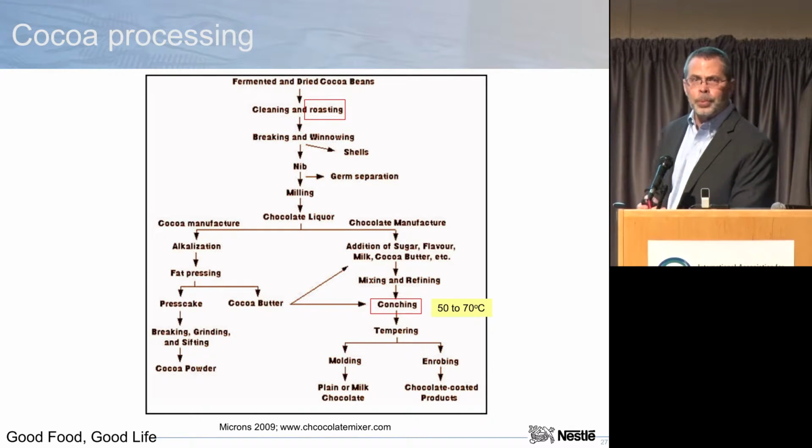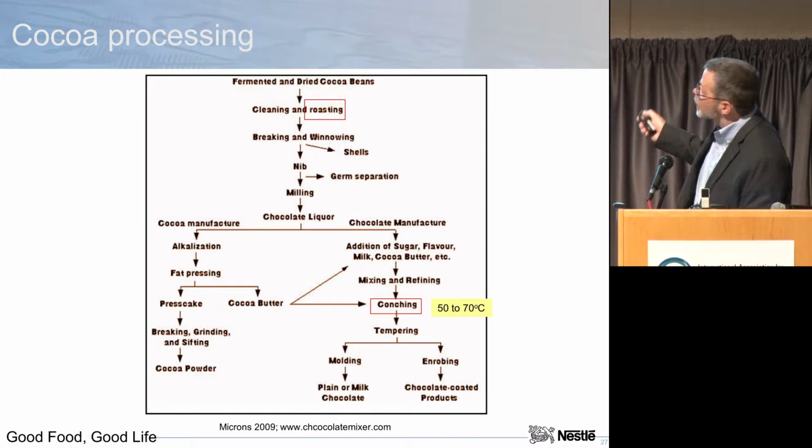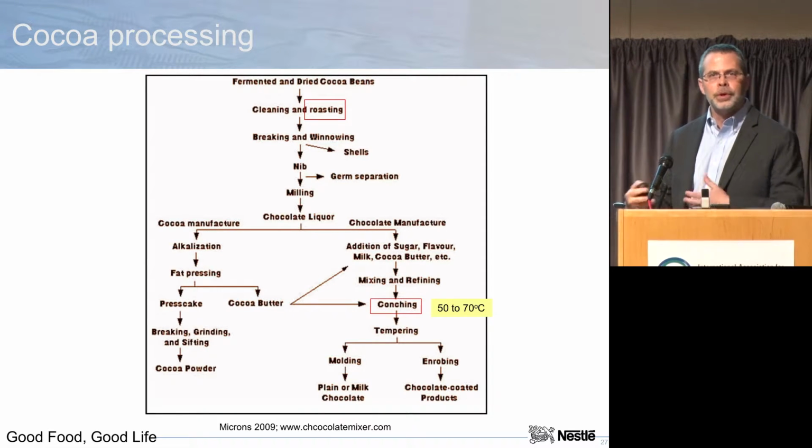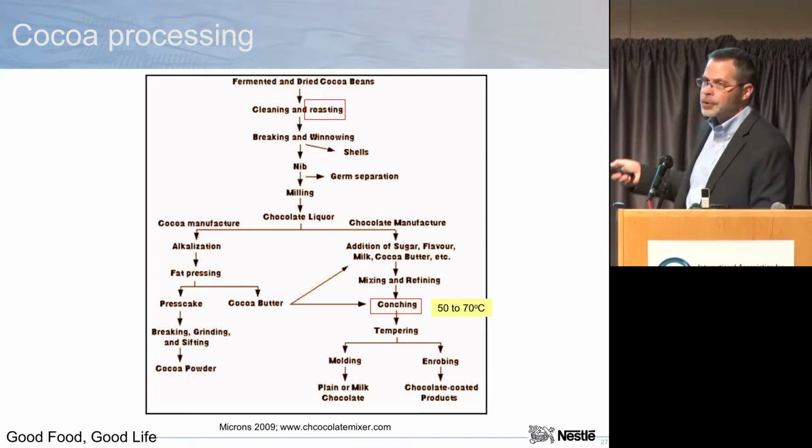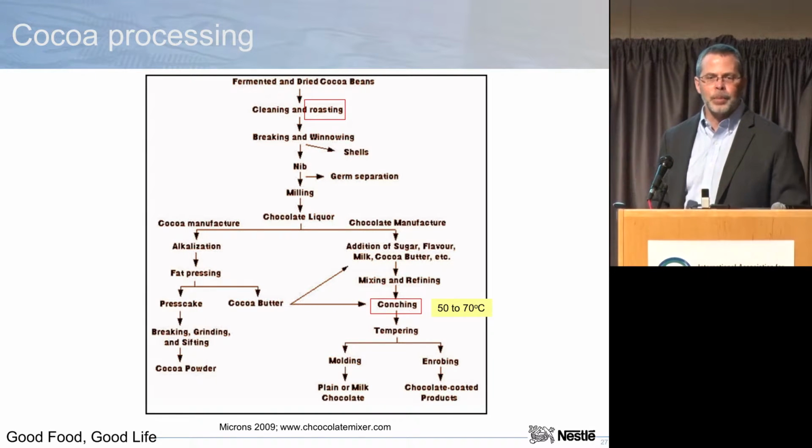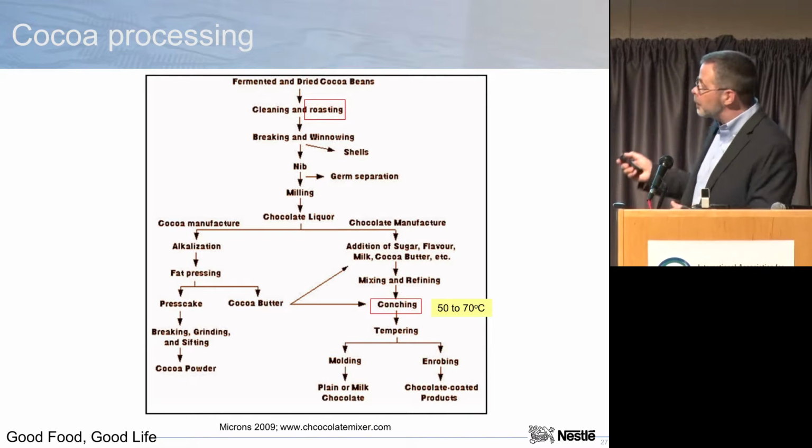Okay, so this is cocoa processing, and in cocoa processing there's a couple of steps where heat's involved. So we know there's Salmonella coming in on the cocoa beans. We want to know where in our process we have that ability to deal with Salmonella. And here I'm talking not just on environmental control, because we know that environmental controls, water control, zoning, those are all critical. But in the process itself, here's the steps.